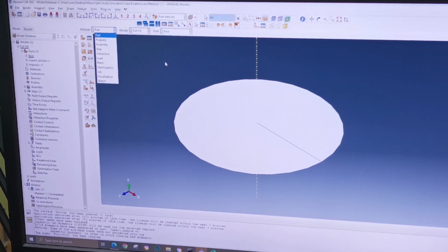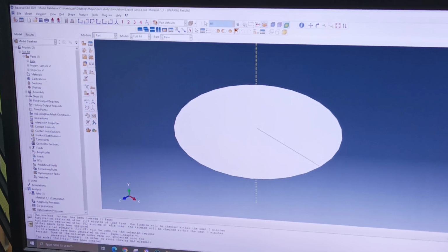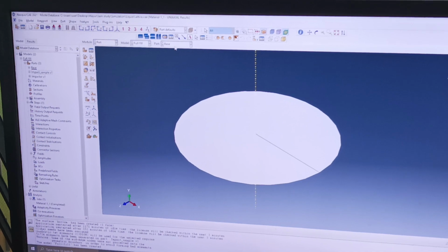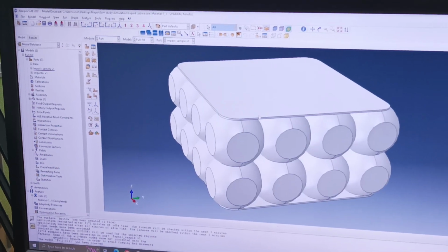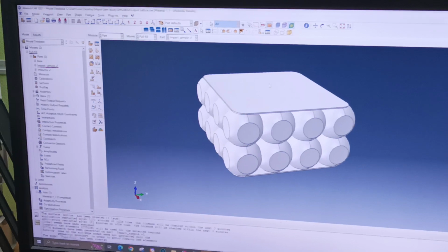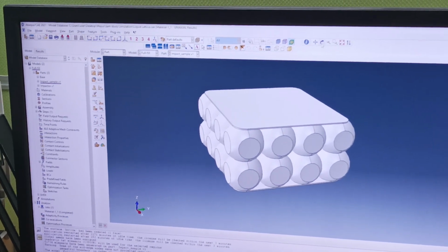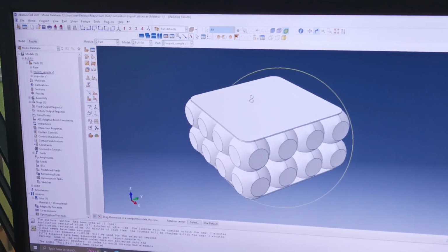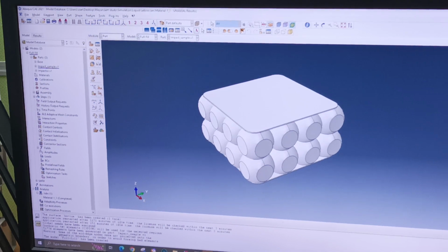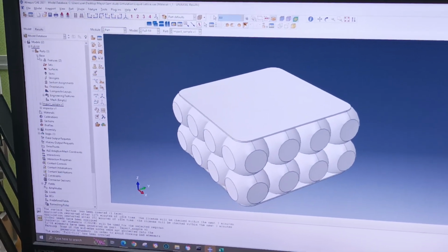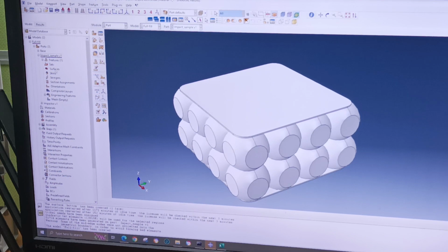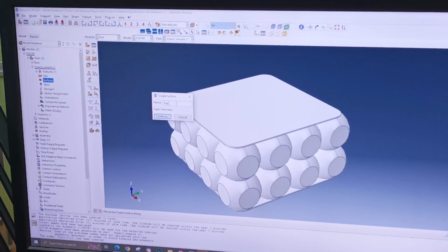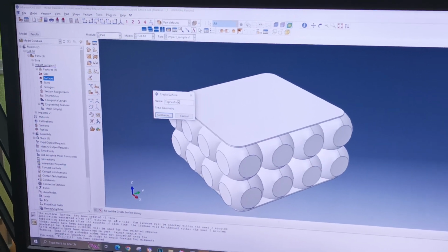Then we import all the parts, right? Another important part is that the software does not know which is the surface. Let's say I have this impact sample. It has to impact on the surface on the top, and there is another surface at the bottom. So I need to define that this is a surface. Otherwise, it will not recognize this as a surface. So let's make this a surface. We go to the impact sample, Surfaces. Double click, open the surface. I just write top surface.